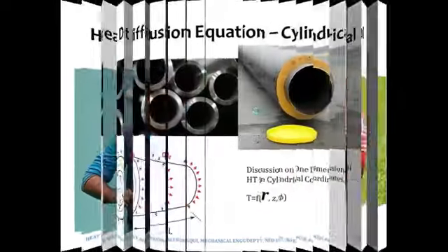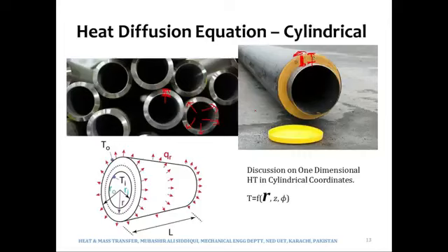See, there is a reason. Over here when we were discussing the cylindrical coordinate systems, if you check the temperature along the length of the pipe carrying steam, you will not find different values of temperature at different points. It means that temperature is not a function of z. Similarly, you will not find the temperature to vary circumferentially, means temperature is not a function of phi even. So if there is a pipe carrying steam or any other heat transfer fluid, the temperature is usually a function of r only. And if it is a function of r only, it will make it a one-dimensional heat transfer case.